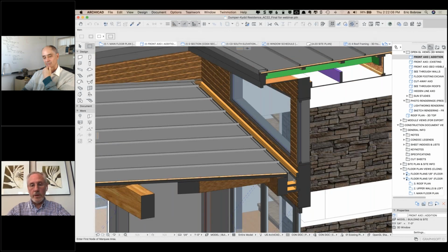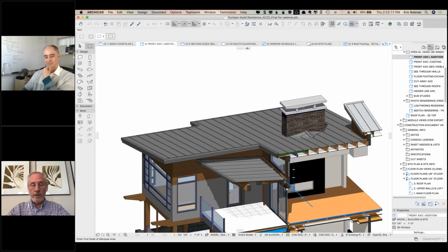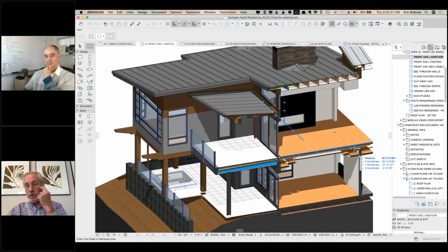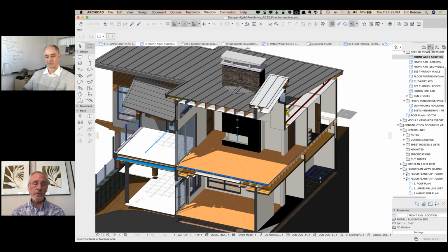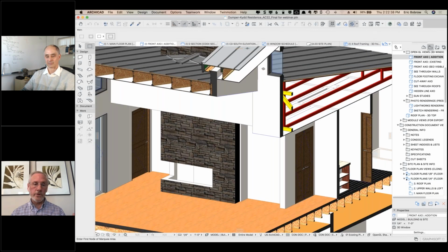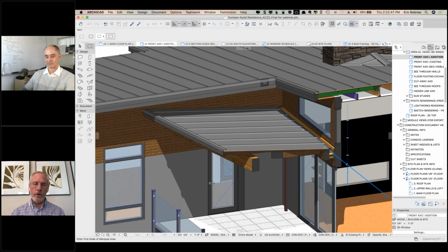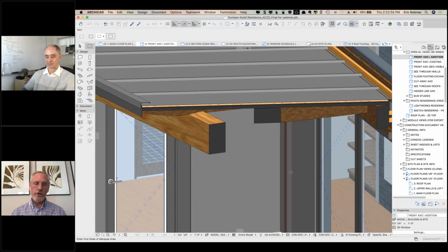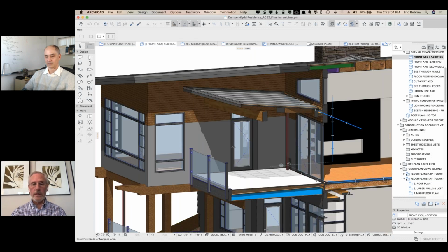Now I did with the builder, we worked out a more elaborate detail of flashing and that kind of thing later. This was just modeled fairly accurately, but just to show where this would go. It does snow sometimes in this location, so we were concerned about snow building up there and or the drains becoming clogged and then water building up in that area. So the builder put in 2 rainwater leaders on that one piece of roof. And we put in some kind of a visual sight gauge, which doesn't show up in my model, but on the outside in the downpipe itself, where the client can quickly check if it's raining really hard. He can check whether water is coming down there. And if it's not, he knows he has to go up on the roof and clean out the drains or get the snow off. Yeah, you can see the angle there pretty well.